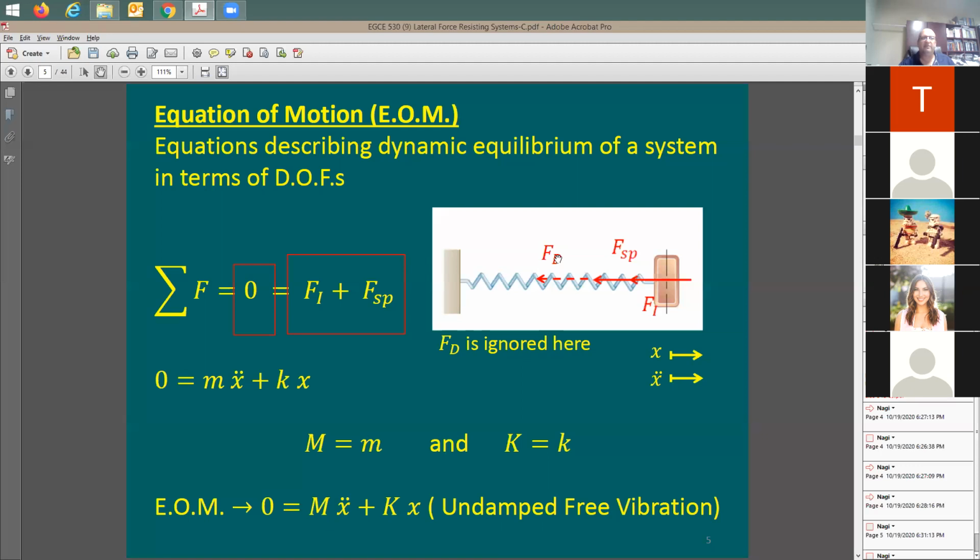Damping force is similar to the sources of damping that we covered in our vibration analysis. For example, when it comes to concrete, the damping effect comes from cracking. When it comes to steel, it also comes from some minor cracks that happen, relocation of the metal particles within the steel beam, and also from the inelastic performance. You're going to have some residual strength, and it also comes from the partitions, and from the connections between beams and girders, bolted connections, and so forth.